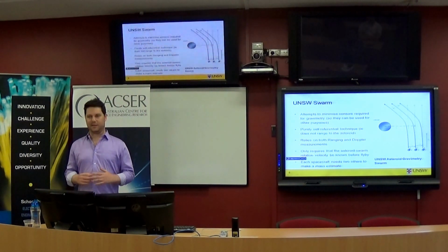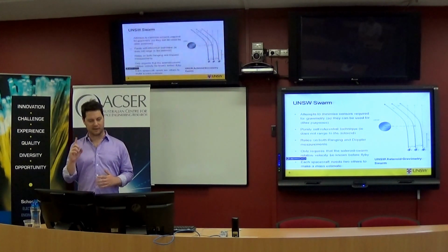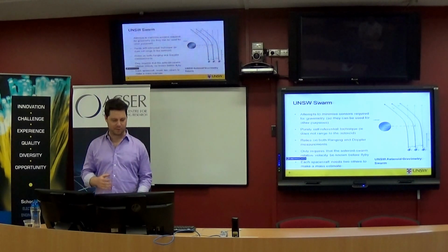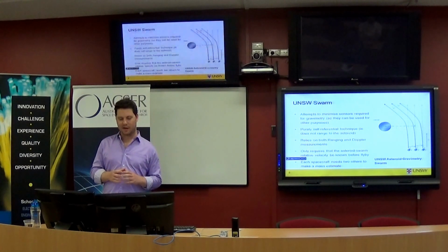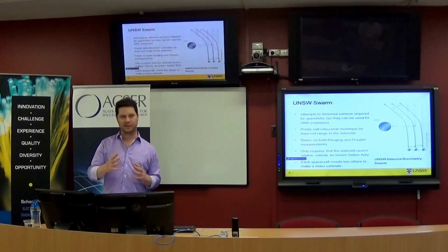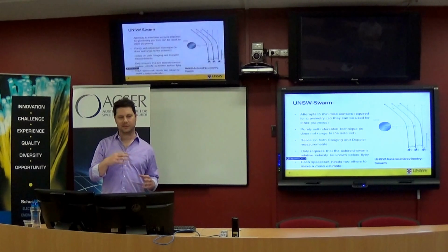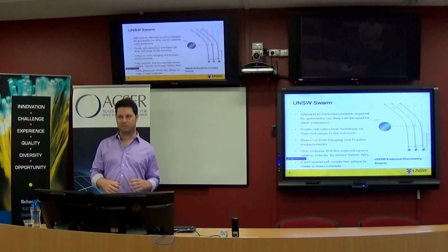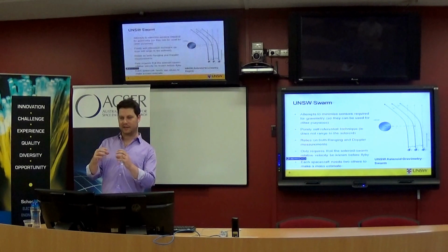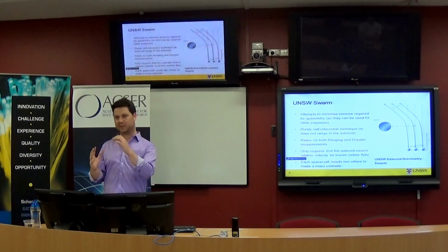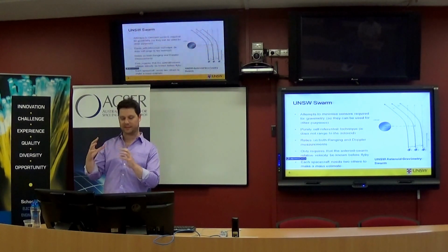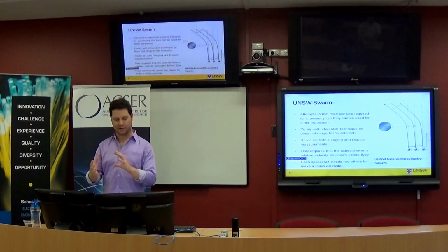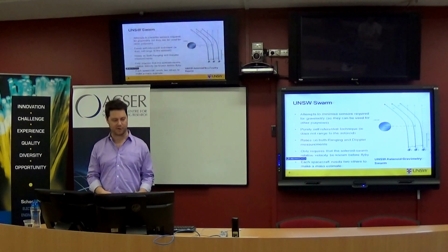So our main ethos is trying to minimize the number of sensors required for gravimetry, so just using communications technology, which we assume will be required anyway. And it's only self-referential. At the moment, when we fly by asteroids and we estimate their mass, we have to reference where the asteroid is located. But we argue that just using the referencing between swarm agents themselves, you can, one, figure out where the agents are relative to the asteroid, but also determine the asteroid mass just from those relative movements.